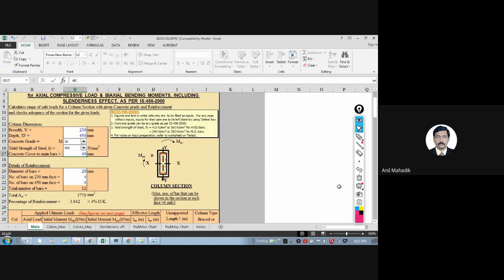In this, say this is your column, these are your bars, and there is definitely a stirrup also, which has some diameter. The software is asking for this distance at the face of the main bar. So our 40 mm distance plus 8 mm stirrups will be 48.